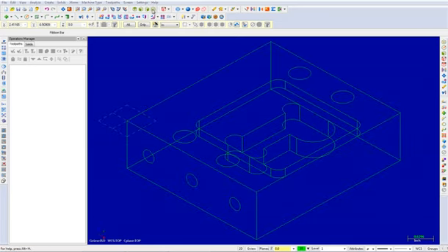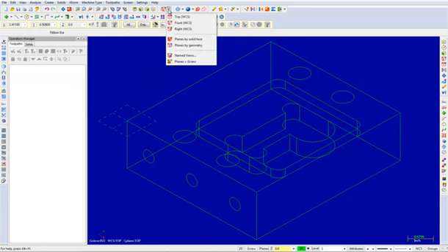We will now create the slot on the left plane. In this step, you will change the construction plane to the right and create a slot using the construction depth to determine the location of the slot. Change the construction plane in graphics view. To do this, select the drop-down arrow next to the construction plane. From the list, select Right.